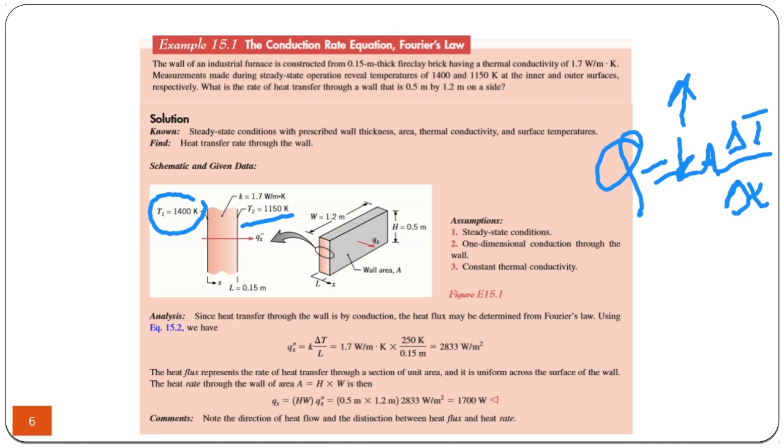So we just want to calculate the heat loss from this wall. You can also do this for your house. You can assume that the wall is 20 Celsius, outside is 10 Celsius, and the thickness is this. From the wall material, you can find out the k. Then you can calculate the heat loss from this wall, and you have a total area of the walls.